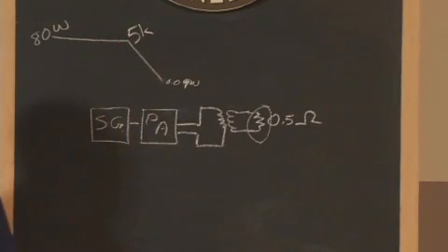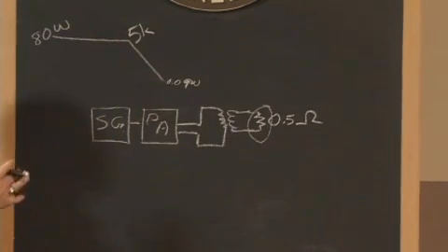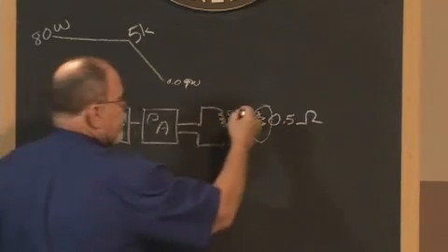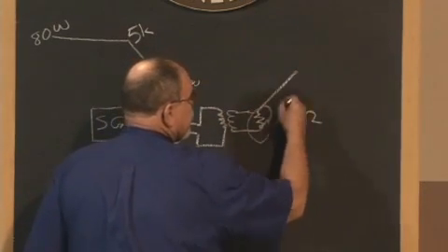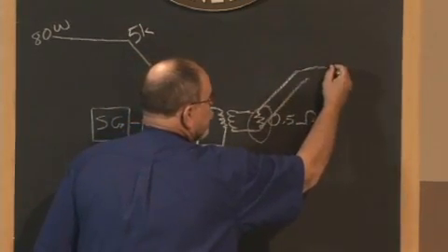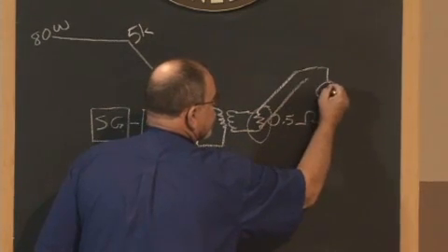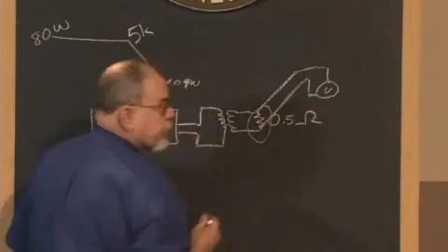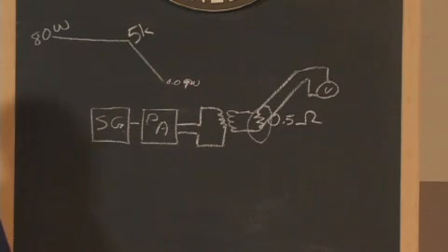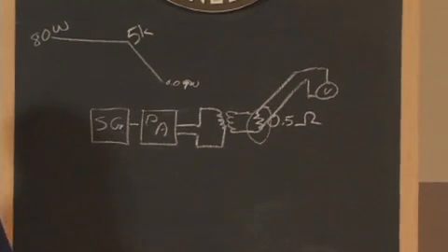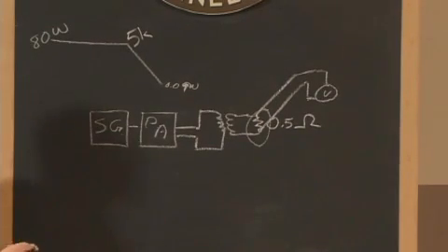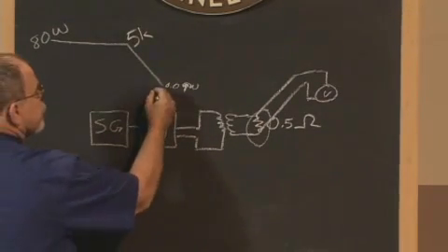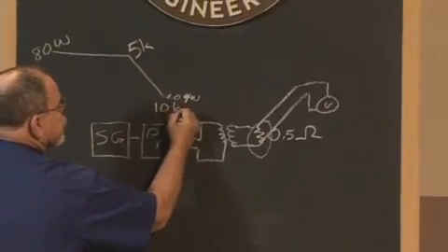So prior to the testing, we need to have a measurement method here. And what we will do is we'll connect a voltmeter of some sort. And the voltmeter could be various things, an oscilloscope, or whatever we determine to measure, an AC voltmeter, something with the frequency response to let us go to the upper test frequency of 10 kilohertz.